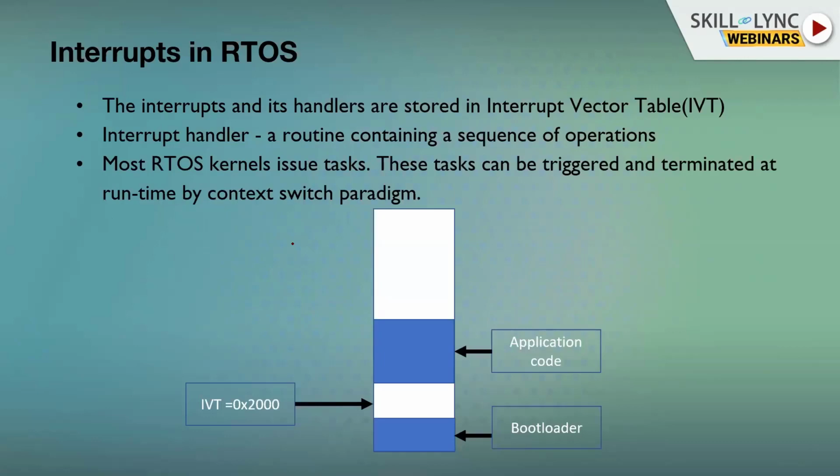Okay, so moving on from this place to interrupts. Interrupts are an undetermined event that is going to happen instantaneously, and these interrupts are usually handled by what is called the interrupt vector table, IVT. Okay, and there is an interrupt handler which manages all the interrupts that are generated. The interrupts may be software or hardware in nature. It is an event that is requested because that event has to happen at that instant of time.